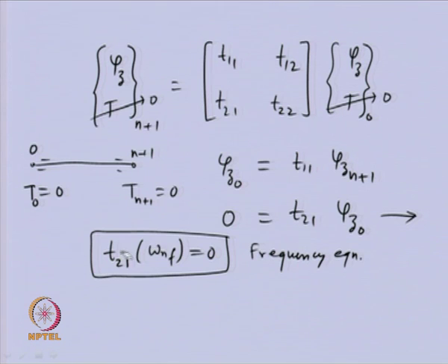This will be in the form of a polynomial, and we can solve for a simple system using the polynomial solution, or by some root searching technique we can find the various natural frequencies. Second, once we obtain the natural frequency, this particular equation can be used for obtaining the field variables related to each other, so that we can draw the mode shape.